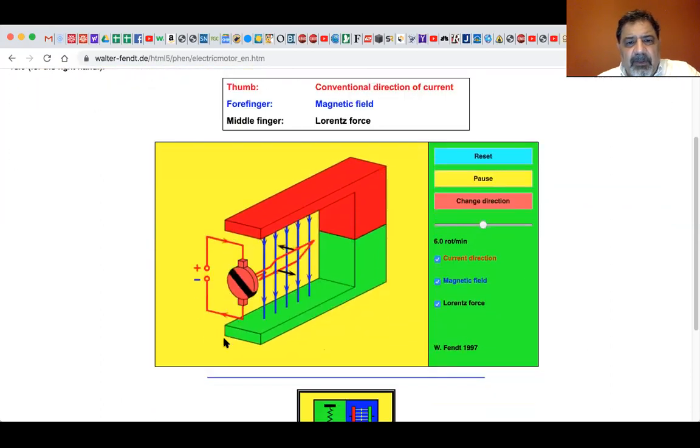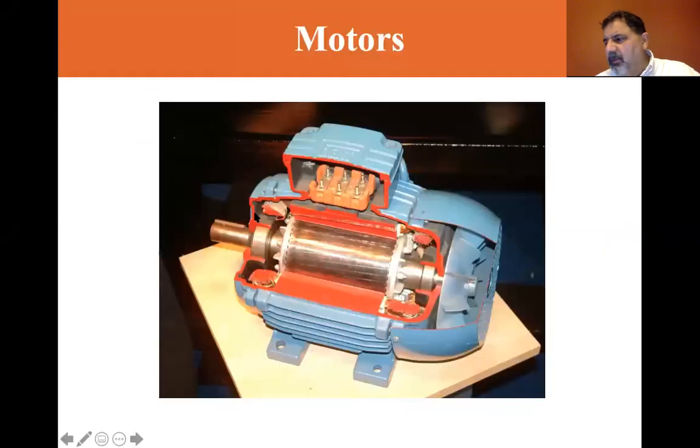There's no hand crank, and this is from the torque. You remember if we put a current in a magnetic field, if we put a loop in a magnetic field, it induces a torque. Well, we take that torque and apply it to some kind of drive shaft, and it'll drive a motor, and that's what we have with a DC motor.